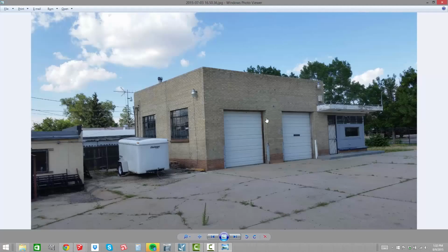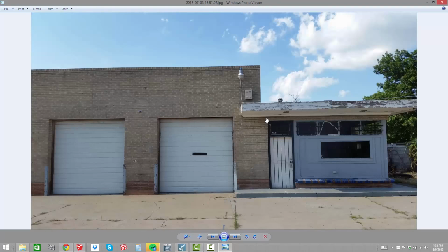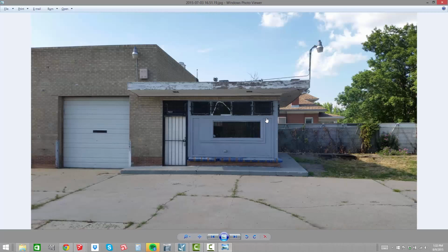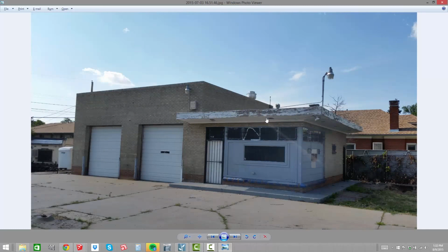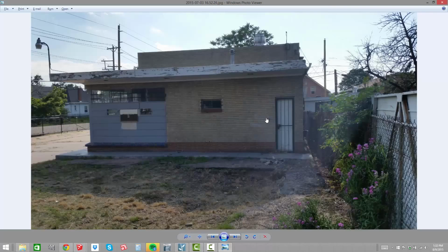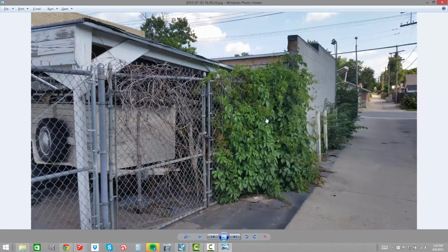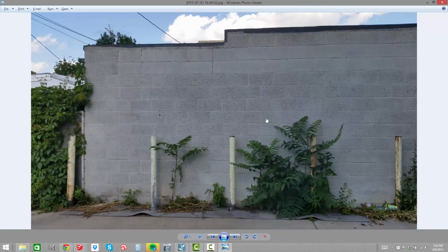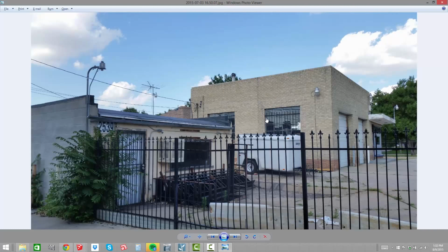What I did first is I went out to the site, walked around the site, and took a picture from every angle I possibly could, because no matter what, if you're building a photo textured model, it is inevitable that you will have a little corner of the building that you miss. So I always recommend taking as many photographs as you possibly can. And it's always good if you can get in there to take some more detailed photos, like for instance a nice shot of this block wall. If I could have gotten in there, I probably would have taken a close-up of the brick, because the brick looks like it could be salvaged.